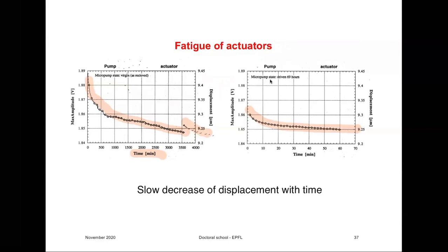What you usually find in this type of device is that it is not the material or your structure that fails, but the interface between them, how you glue that piezoelectric disc to your structure. That's usually a weak point. Interfaces very often are weak points in material science. So what kind of glue you choose matters.